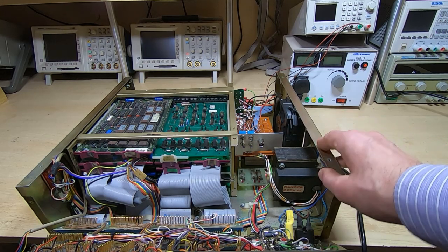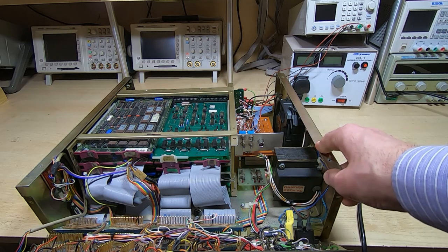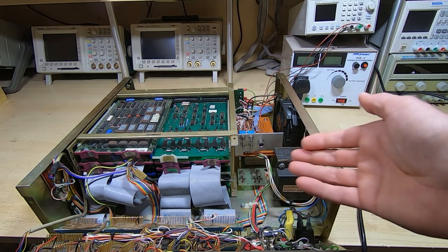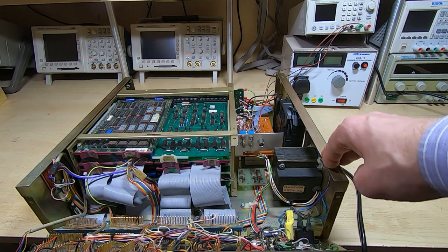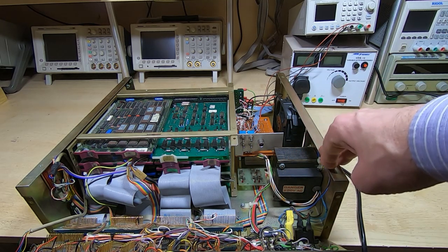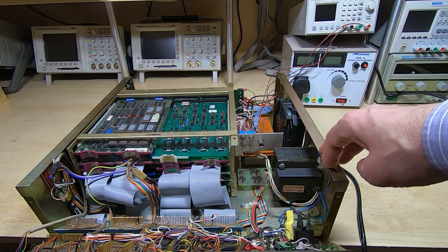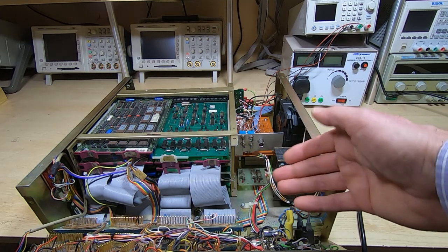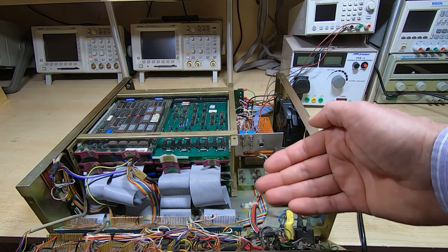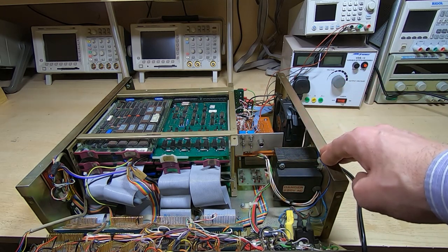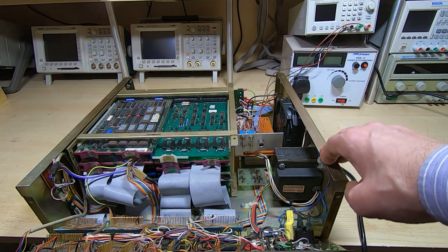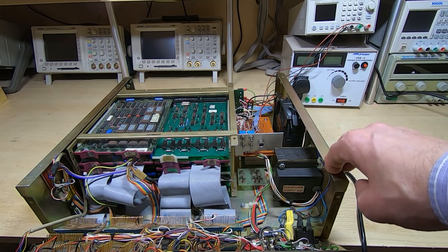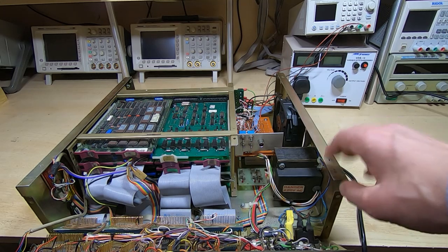Now, in CNC machines, one of the important aspects is timing, and because it's multi-axis, I think this machine can support up to 6 axes at once, in a CNC environment you have to control all the axes in a very timely fashion, otherwise you'll get stepping in the CNC machine itself, which you don't want.